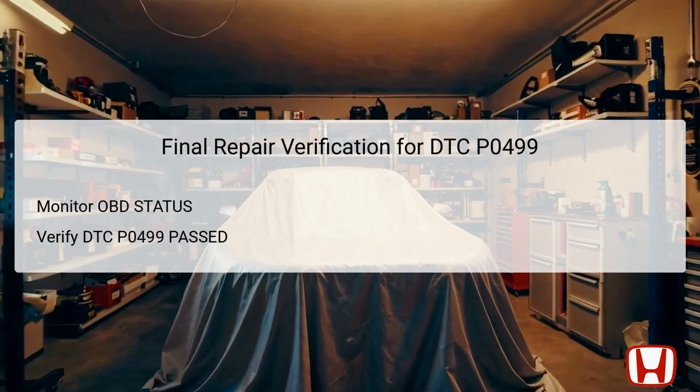After completing all necessary repairs and adjustments, the final verification step is crucial to ensure the effective resolution of the DTC P0499. Utilize the HDS to monitor the onboard diagnostics, OBD status, which provides a clear indication of the vehicle's emission control system performance.